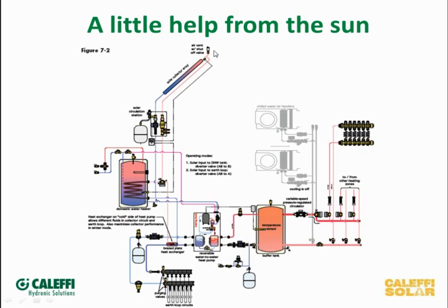So now we've got some solar collectors on the roof, a little solar pump station there. This would be a closed loop glycol system. So now this has to be separated from the water that's obviously in your domestic water tank and also in your heating system here. So what we're doing is bringing our solar in through one of our solar pump stations here, and we're bringing that into the coils in our solar tank here.